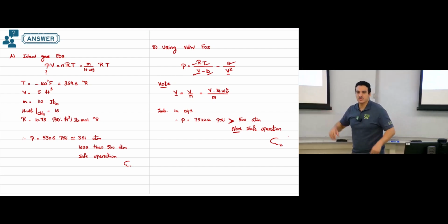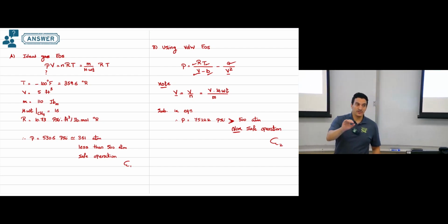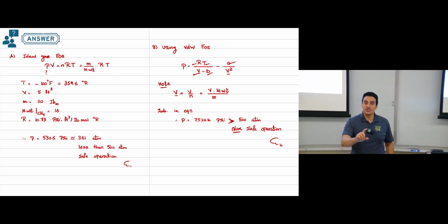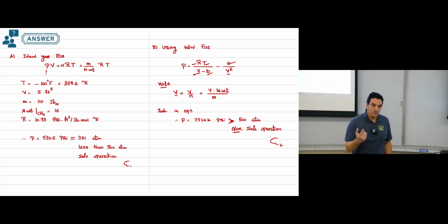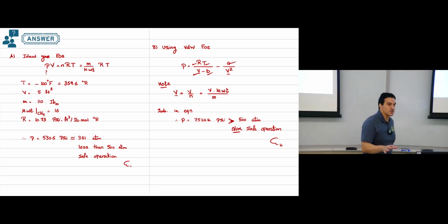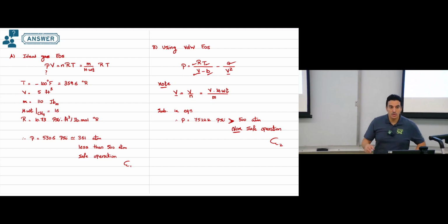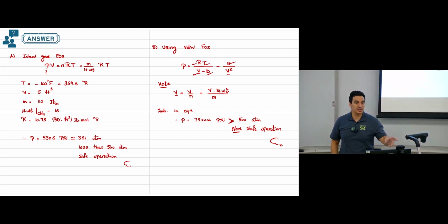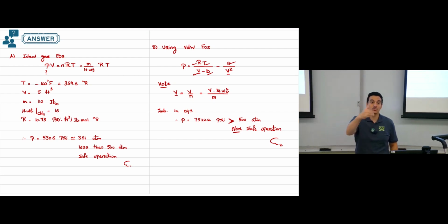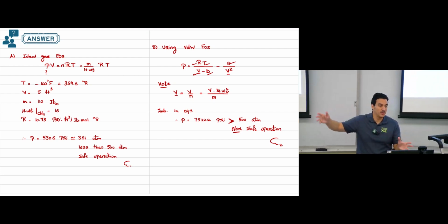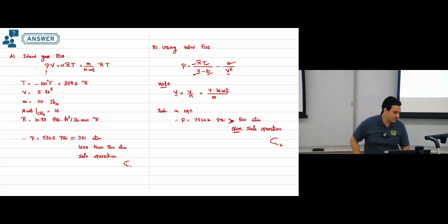So you see the differences we have here. You have a process and an issue happens to this process, and as an engineer you need to take action. How can you take this action? Just calculate the pressure value. Based on the pressure calculation, you can know whether your process is safe or not. You can use the two equations that we have shown. One of them tells you everything is safe and there's no action required from you. But the other one tells you that you have an issue. You need to take action because the pressure is more than the failure pressure that the unit can withstand.